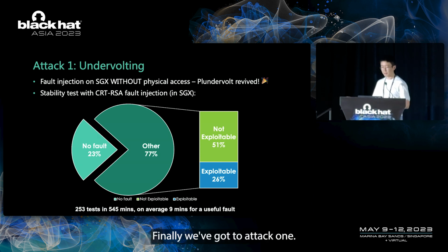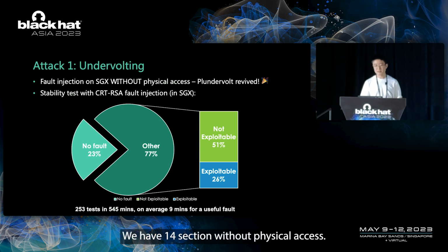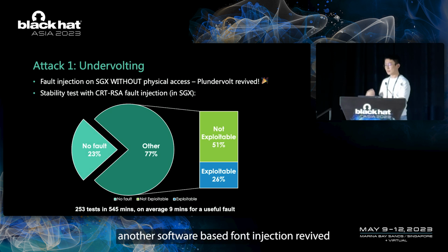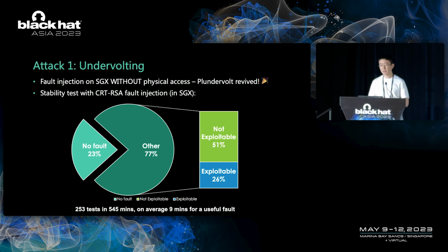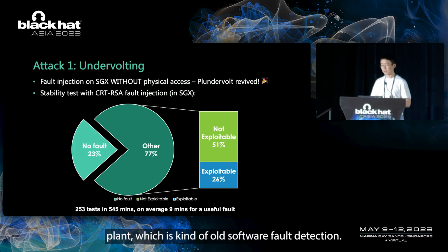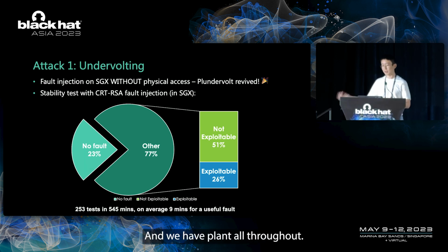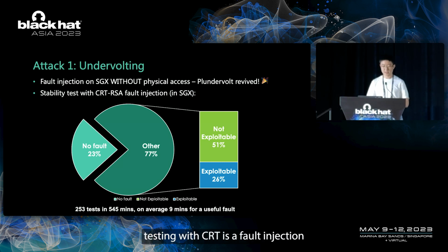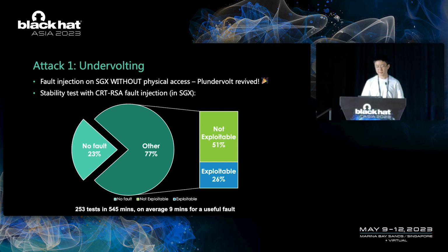Finally, we got attack 1. We can do fault injection on SGX without physical access. That means we have another software-based fault injection revived. Plundervolt was a kind of old software fault injection, and we have Plundervolt revived. We also did some stability testing with CRT RSA fault injection.